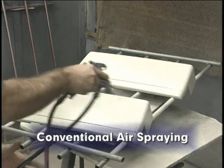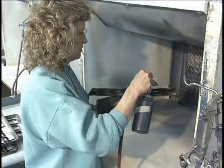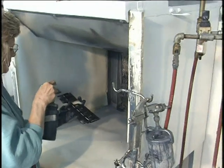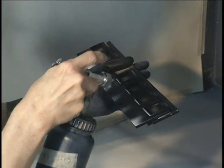Conventional air spraying uses highly compressed air to atomize the paint, which is applied using a spray gun. The paint is fed to the gun through either a gravity, siphon, or pressure system. The paint may be applied manually, semi-automatically, or automatically.